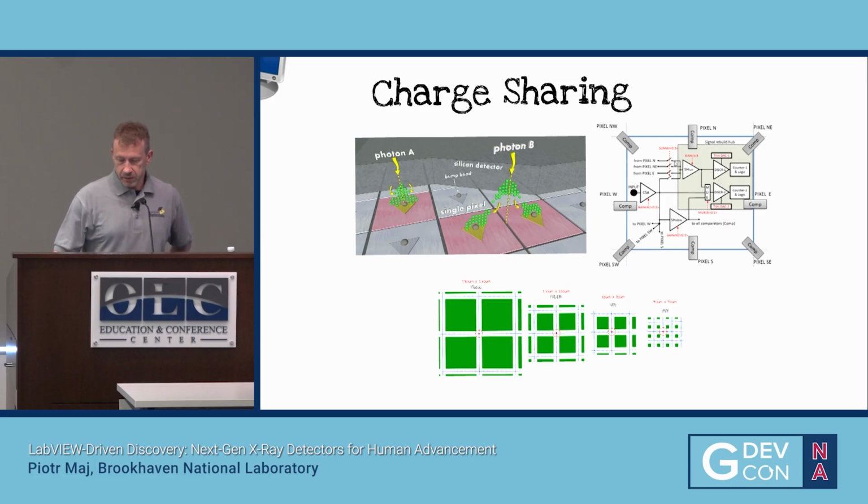Let's sum all the data together and then put comparators between a certain channel and all the neighbors. Sounds easy, but the pixel size usually is less than 100 micron, so the solution is really squeezed inside. Then we have an idea how to verify if it works fine. Of course, in simulations. Then we have to develop those simulations.